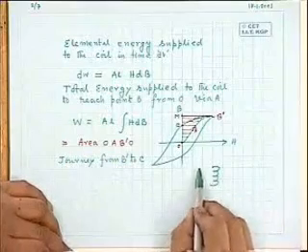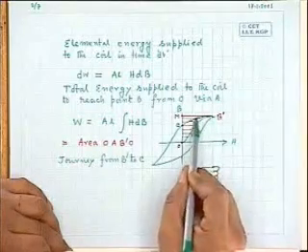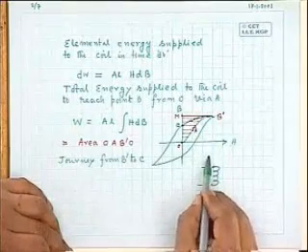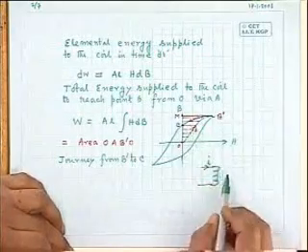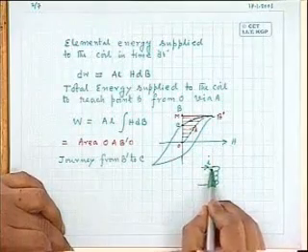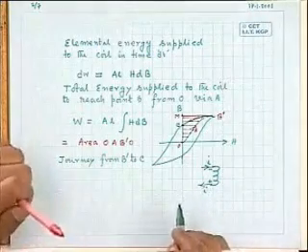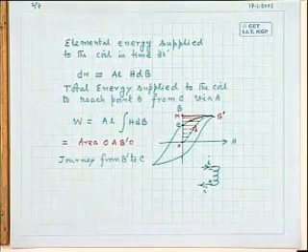Draw the coil once again. At that time, is the current positive? When it is coming this way, positive, because H is positive. So current really is entering through this terminal. Is dB dt positive? No, B is decreasing with time. So the polarity of the voltage induced across the coil is this one. So far as the coil is concerned, is it absorbing energy or delivering energy? It is delivering energy. Like a battery, through the plus terminal current is coming out. So it is delivering power, pumping power back into the source.